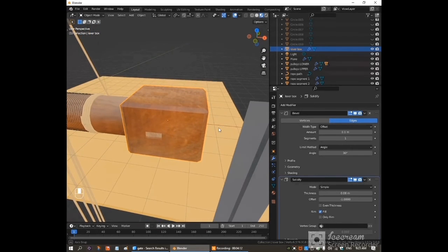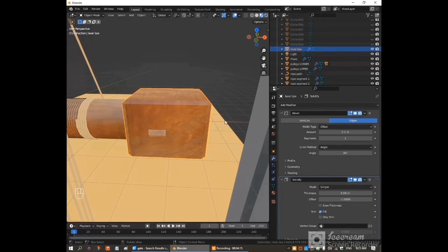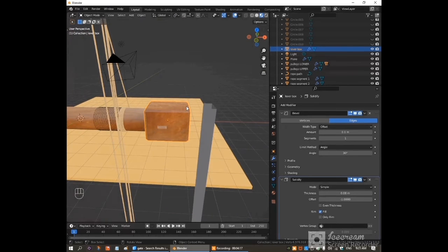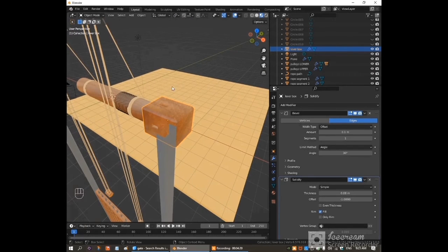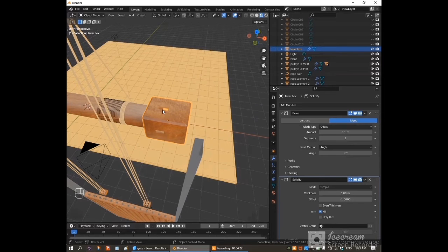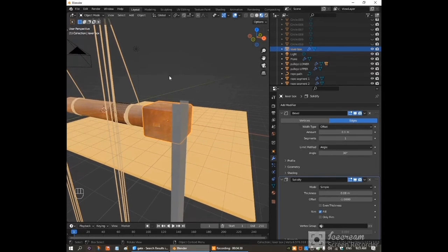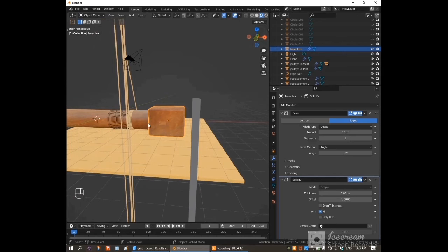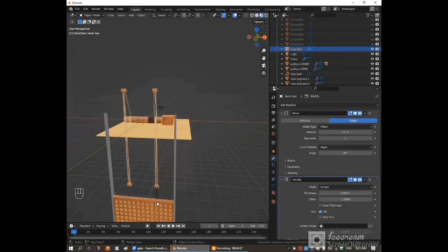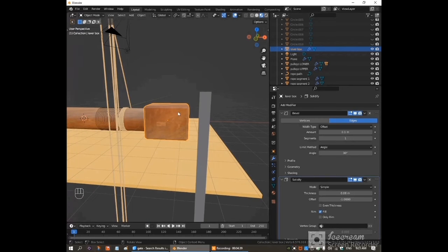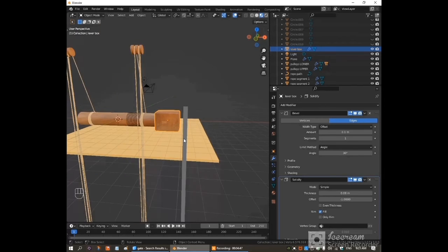So in the castles, when the guards wanted to raise the gate, they would have this long stick, and they would put the stick into the notch here on the top of the lever box, and then they would just pull it back, and that would rotate the winch and pull the rope and pull the gate up. And then when they did it enough, the next notch would be on the top. They'd take the stick out and put it in that one.